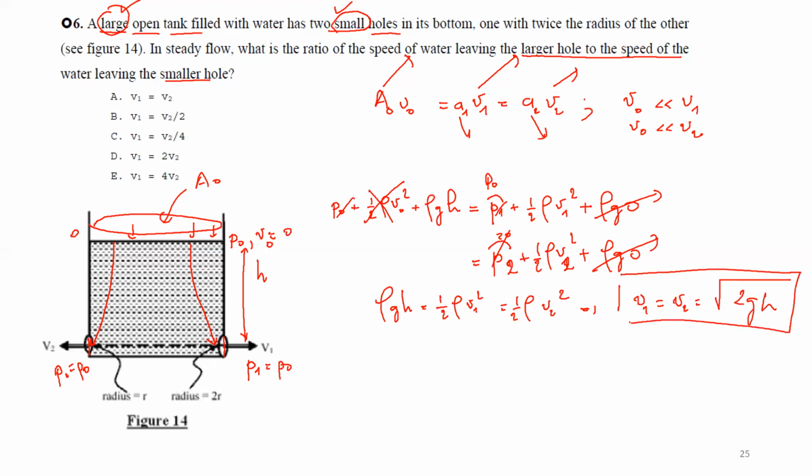And this is extremely important, and we demonstrated this in class already. Basically, it looks like water free falling from a height h. I drop water with initial speed at rest, V0 is equal to 0, from this certain height. This is the velocity of water when I fall freely from rest at a height h. V final here, as you know, is the square root of 2GH. Okay, so that's the speed. So basically they are equal. V1 is equal to V2.